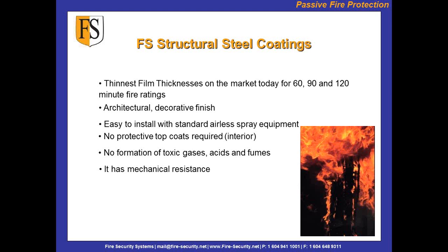You can run an average of steel sections to an average of coating thicknesses, which will give the customer a good idea of where they're heading with that pricing. But you have to provide the steel section, because steel coating is an engineered system with defined film thicknesses based on that steel section. We need it to understand what you're trying to protect, and how long you're trying to protect it